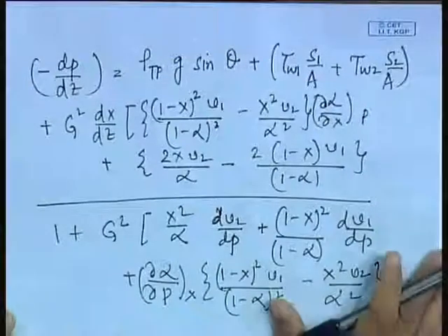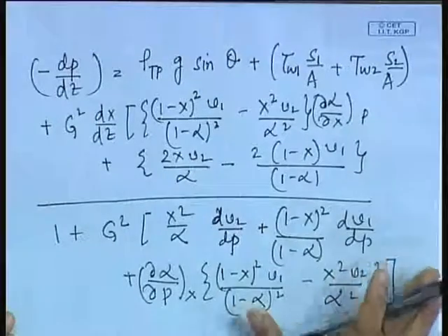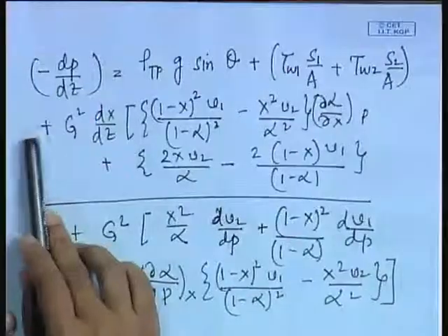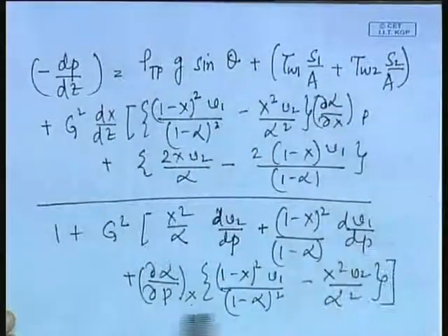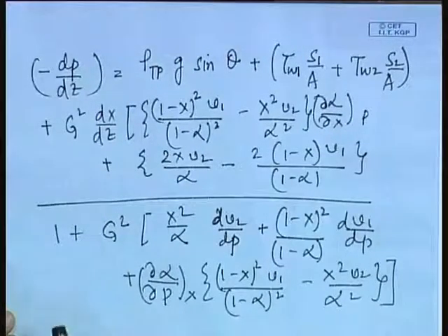Now, after that, if you see what we have done, basically our intention is simply to predict the pressure drop for two phase flow under separated flow conditions. Okay. For that we had written down the momentum equations, and after writing them down, we combined them to find the mixture momentum equation, and the final expression we have got is this particular whole equation, which enables us to calculate pressure gradient from known input parameters.